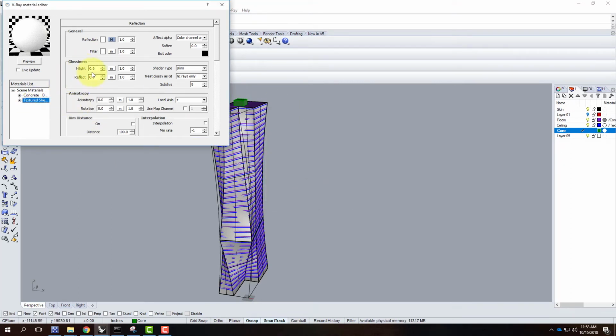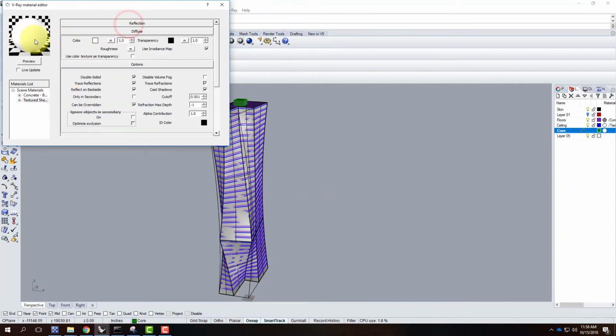This, by the way, in your sheetrock material here, if you wanted to change the color, if you wanted to paint the ceilings a different color, all you have to do is change the color of the material. And it'll do it. It does have some texture on it, so it's meant to have a little bit of texture. You can change the color just by clicking on the color. There are some websites, I should give you guys a link to it, where you can actually figure out what the color of various paints are. So if you knew that you wanted a specific Behr paint, you can figure out what the color is and then put it in here and have that color. So you could change that if you wanted.